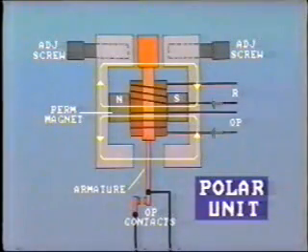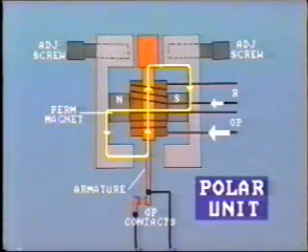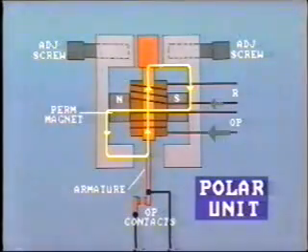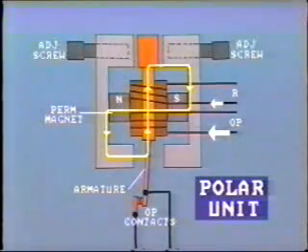The situation does not change when current flow is such that the strength of the operating and restraining coils are equal, since the flux produced is in opposite directions and cancels out. When current flow is such that the flux produced by the operating coil is greater than the flux produced by the restraining coil, the armature will move, so closing the tripping contacts. The tripping point can be adjusted here.